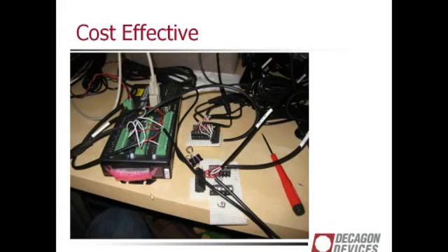Okay, this is the setup. We've got an SDI-12 compatible logger here with 2 buses. On a logger like this, there are 4 communication ports. So normally, without using SDI-12, you could put 4 digital sensors on here, and that's it.